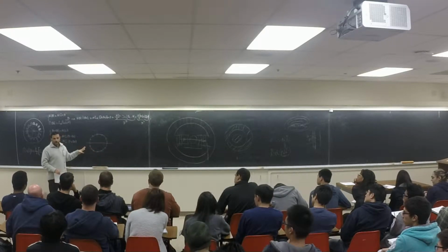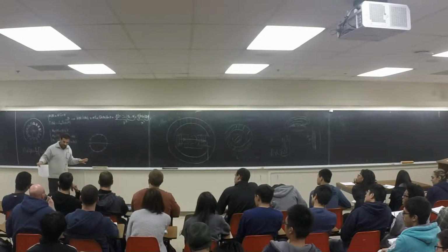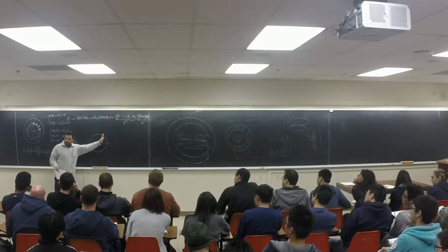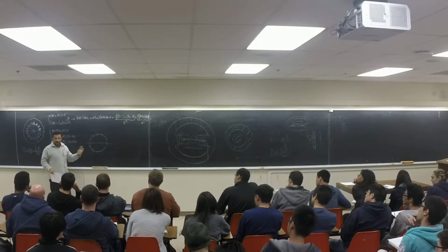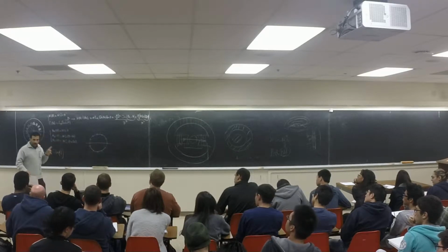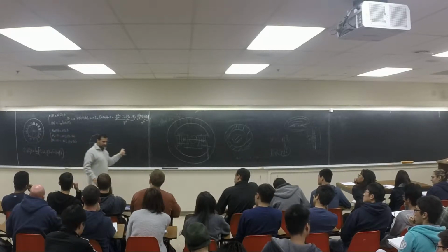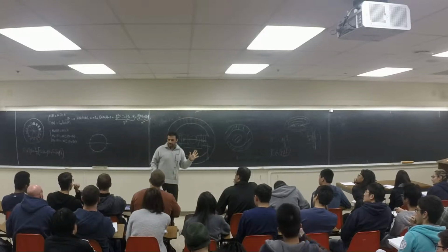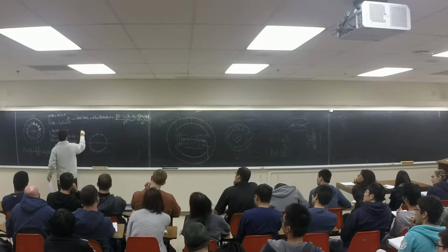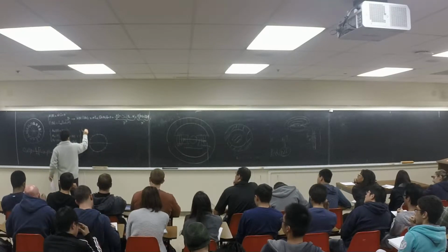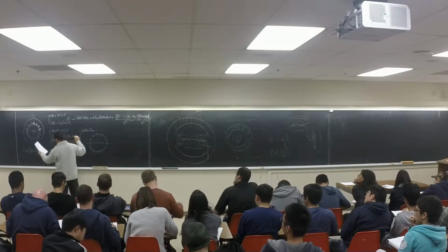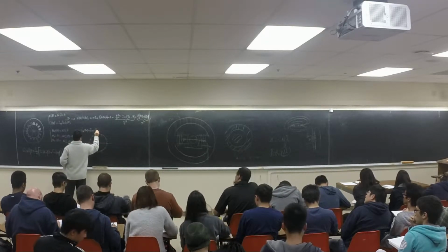My point is, don't think I'm going to have 3 sets of slots for each phase. You come up with 1 set of slots in the machine, and you start to put this winding there. Now, I have a 3-phase winding. Each one sinusoidal, like this, right? I'm going to connect it to a 3-phase source. All of you know what's a 3-phase source, right? I'm going to inject this current, IA, theta E, will be IM cosine omega t.